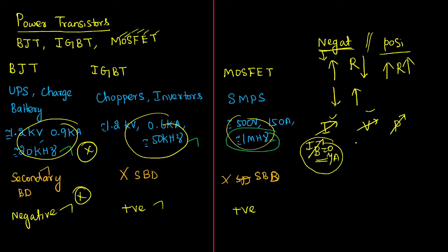When you go to IGBT or MOSFET, everywhere they will be talking about a voltage. Often that is called gate voltage. What is the value of the gate voltage? We keep comparing it. This gate voltage will be compared with the threshold voltage. Is it higher or lower than that? That is the minimum amount of voltage that is required to turn on your device.